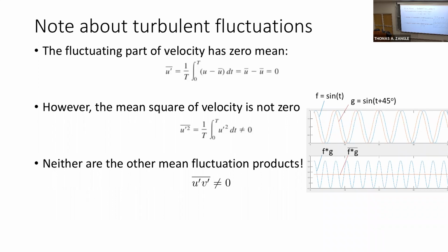So this is saying it's the time average of U prime times V prime. If we did the time average of U prime and the time average of V prime separately, we would have 0. But here we're taking the time average of the product.